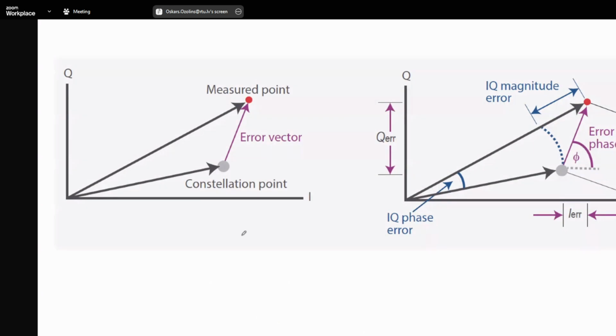So right, there's also a bit more definition of error for the Q component and error for the I component, and then you can define it over a number of different symbols. You can define EVM for a single constellation, even though you really look at each point and many of these vectors. Right, and then you can look at it in the XY plane, or you can look in polar coordinates where you have a phase and an amplitude. So there are different ways to express it.